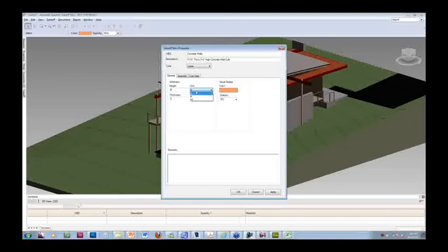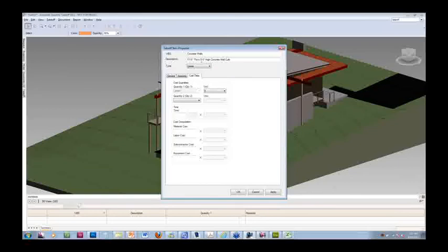And you can do feet or units or inches, whatever. And then the thickness, you can tell it what it is. So maybe this is 9 feet, and this is 6 inches. So you can easily track this once. You can add a formula if you want here, so you can do wall length divided by the area, or you can really customize your assembly object.